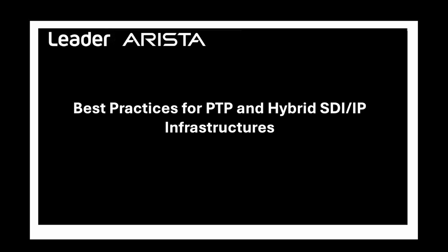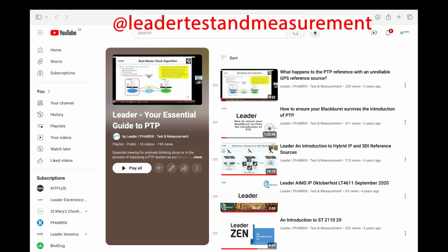Jeff, next question. Right, so let's move on to the subject of hybrid IP and SDI environments and how PTP and Blackburst and tri-level sync can coexist. Now, we have done a whole session on this one, Steve, so for those who haven't, I'd recommend visiting our YouTube channel and catching up on that. But for those new to it, Steve, what are the key points that you would recommend? Because let's be honest, nobody has a completely IP facility. Somewhere in there is that one device that's got SDI and it wants Blackburst or tri-level sync as a reference.